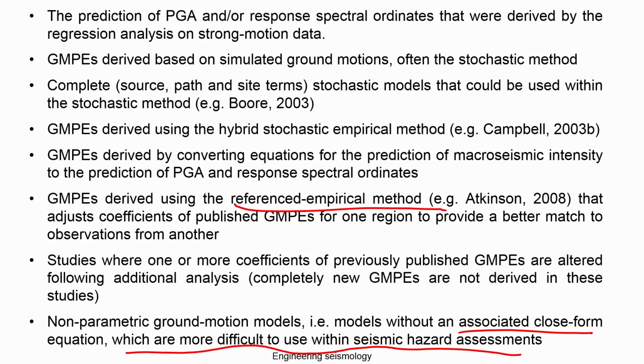For example, for peninsular India there are about 3-4 regional equations, and with the outside regional equations, around 13-14 GMPEs are available, but all of them may not be applicable to your region. Similarly, in North India, some of the equations may not even be suitable for hazard analysis.